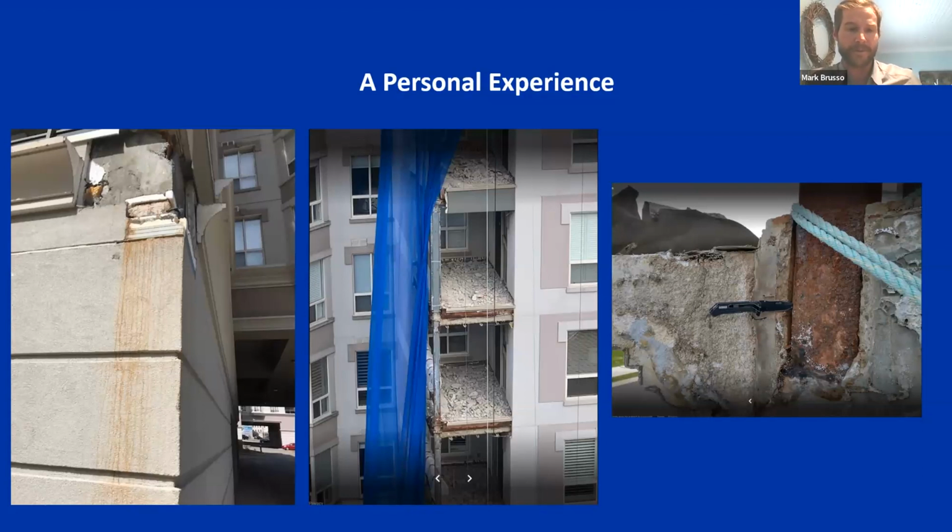I haven't been working for that builder for quite some time, but through reading the newspapers, I found that the weep system, the weep holes in the EIFS system, were left completely out. Water getting in behind the system over time had become trapped and led to a huge amount of corrosion requiring extensive repairs. That one little detail that was left out of this project resulted in the need for the EIFS system to be completely replaced and reclad, and also some extreme corrosion over the long term.